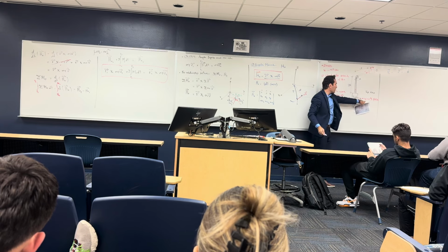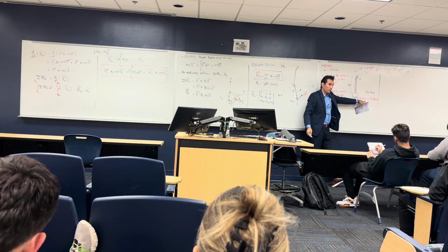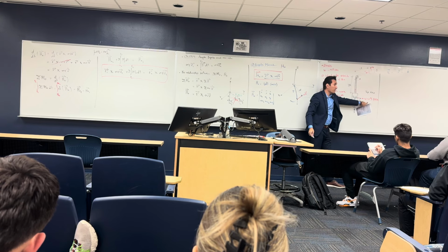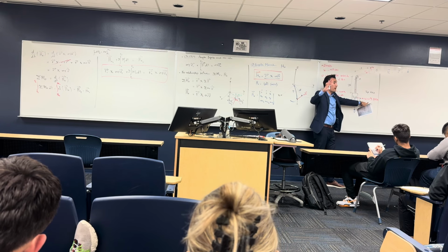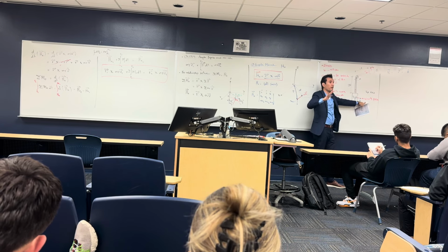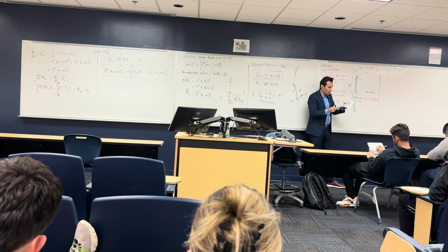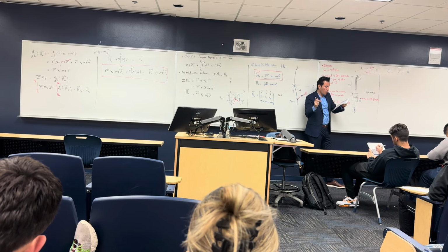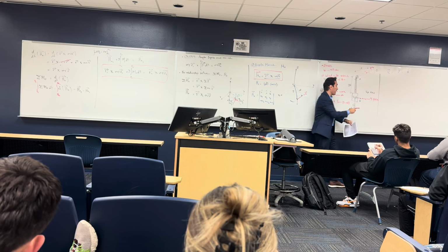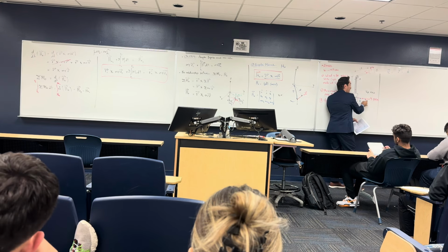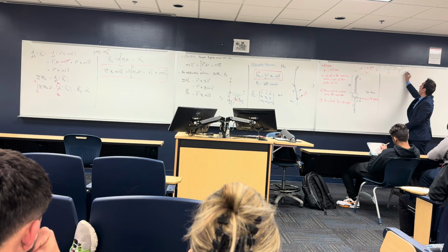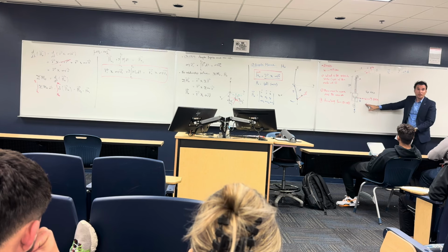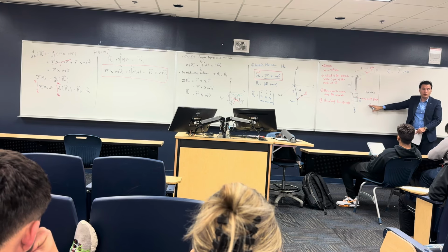So is V1 VR or V theta? The one that is given. I said it's V1, but this is not the whole velocity. It's a V you need to figure out. Like I gave you in the problem, the crate is moving with V1 of 0.5 feet per second in a straight path. So this is actually V theta. So I have 0.5 here, and it's positive because it's in the same direction of the motion, right?